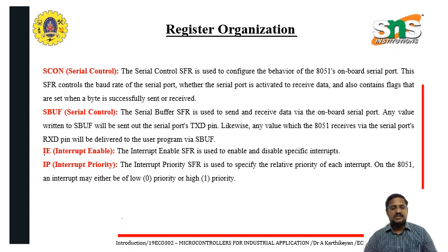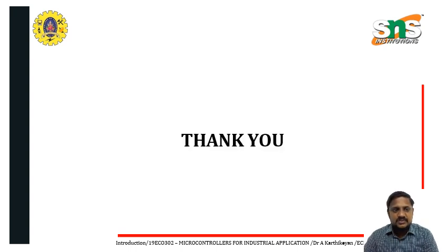SBUF is the serial buffer SFR used to send and receive data via the onboard serial port; any value written to it is sent, and any value received via the serial port is read from it. Finally, IE and IP, the interrupt enable and interrupt priority registers, can be used for other applications. Thank you.